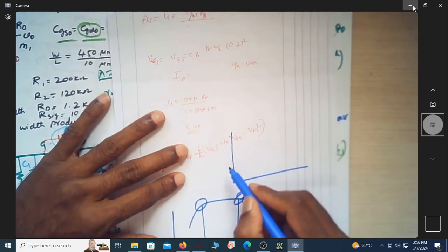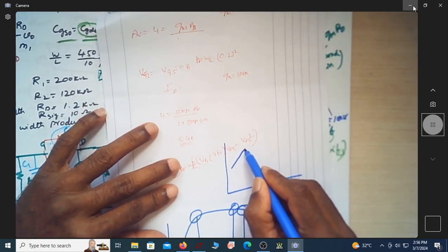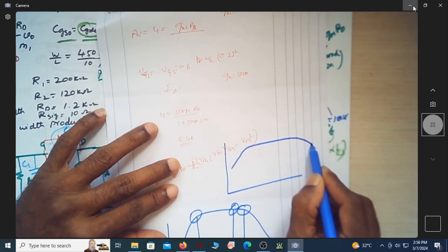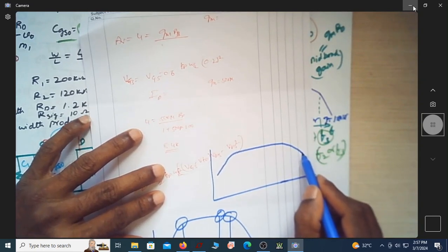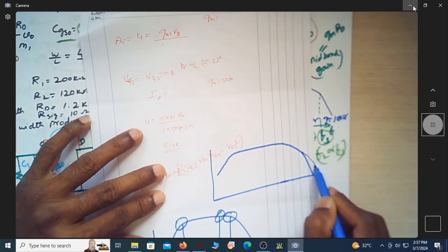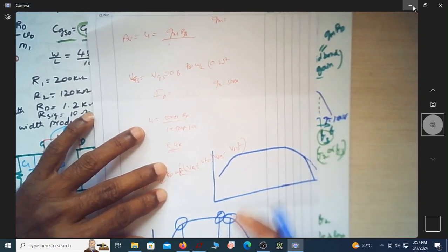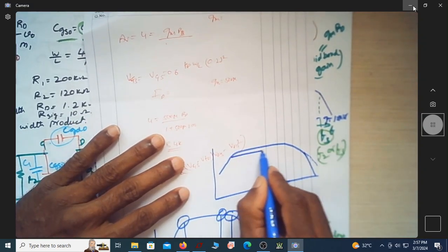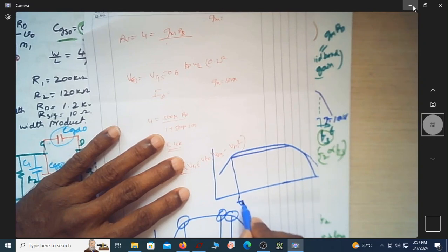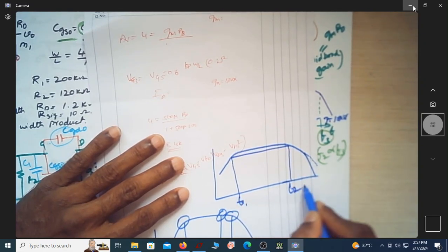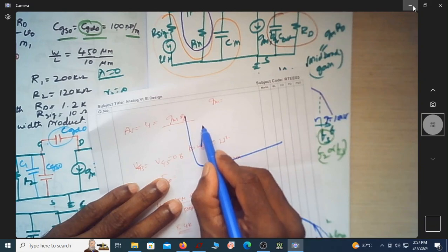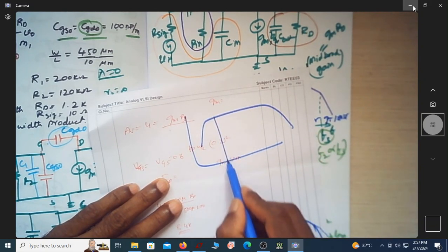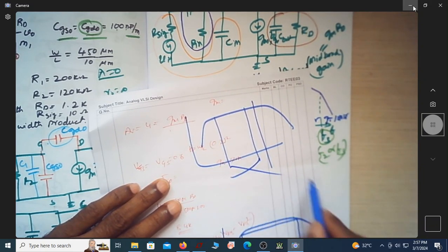When you're writing the frequency response, carefully write something like this. It goes like this, then there is one change in slope, and the slope should change again. Can you see? There should again be a change in the slope. So it comes down by 3 dB. So this is F1, this is F2, and F3 you can approximately write wherever there is a change. Please, for God's sake, don't casually write the frequency response like this. So this is totally wrong.